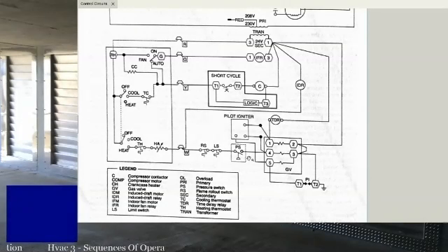The unit will continue to run until the room thermostat is satisfied. When the heat thermostat contacts open, the gas valve and induced draft relay are de-energized, shutting off the burners. The time delay relay is also de-energized. Time delay occurs after the relay is de-energized. This allows the indoor fan motor to continue to run after the burners shut off to recover residual heat left in the heat exchanger. So maybe I lied.